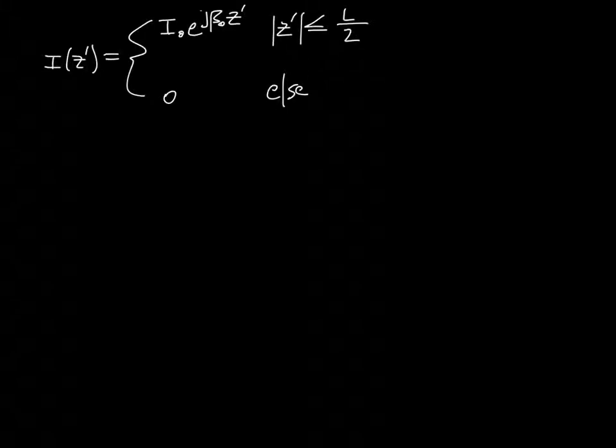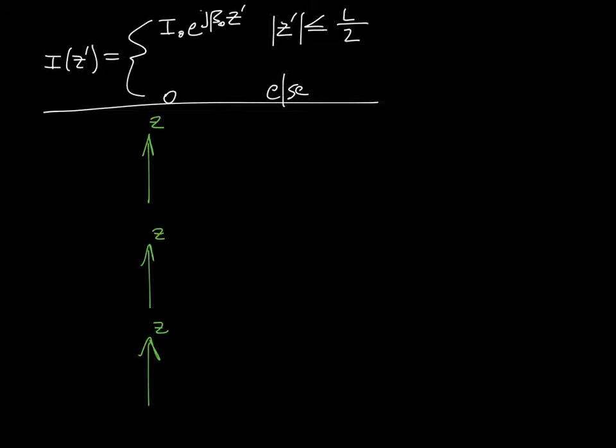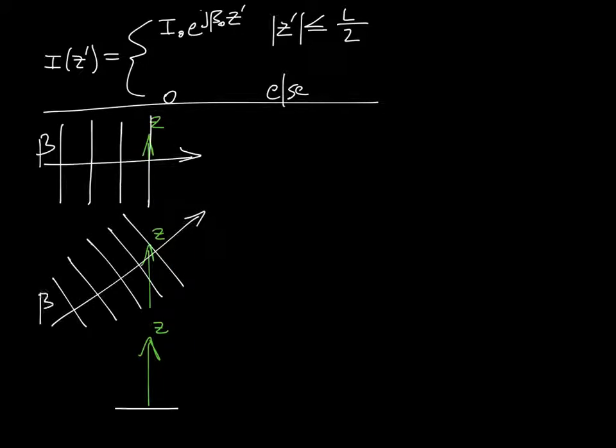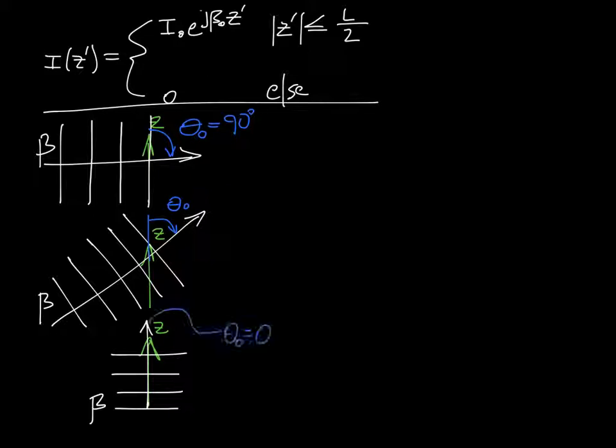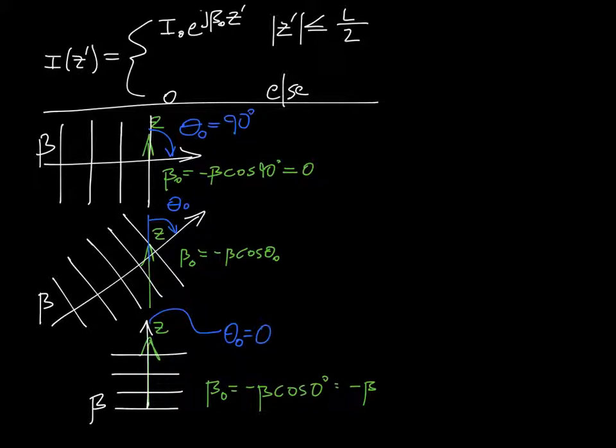In order to illustrate the mapping from the U space pattern to the theta space pattern, I'll introduce this uniform current with non-zero phase, which can be thought of as having a free space plane wave with propagation constant beta incident on an oscillating dipole at an angle that results in the propagation constant of the oscillator beta naught that could or could not be equal to beta.